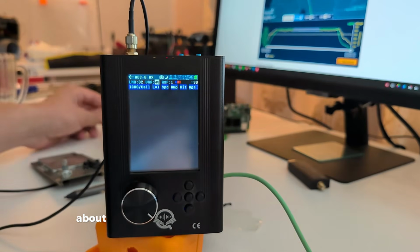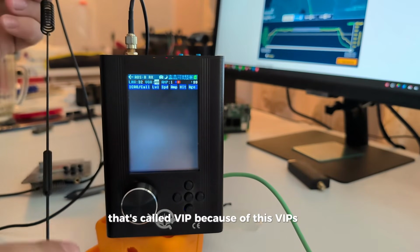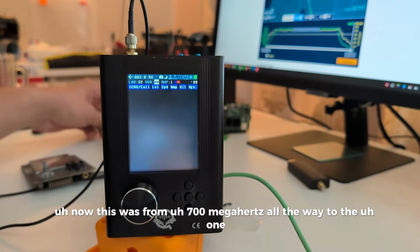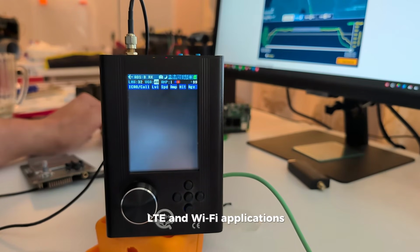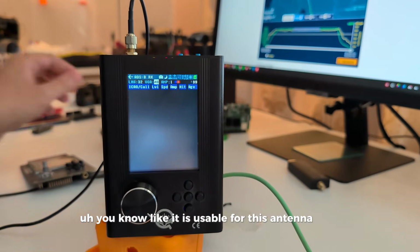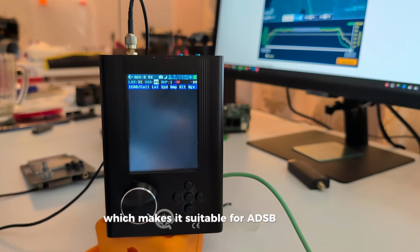About the antenna, I was using the whip antenna from 700 megahertz all the way to 2700 megahertz. This type of antenna is typically marketed for GSM, LTE, and Wi-Fi applications, like 2.4 gigahertz Wi-Fi. But it also covers 1090 megahertz very well, which makes it suitable for ADS-B reception.